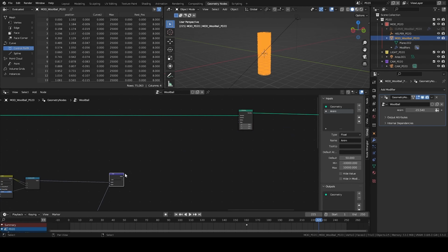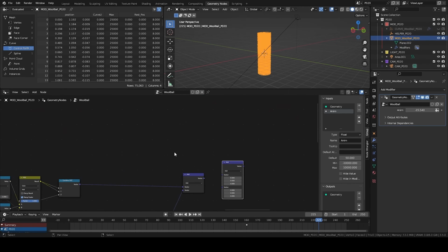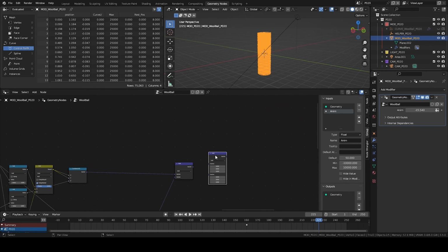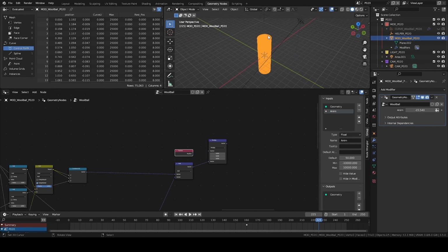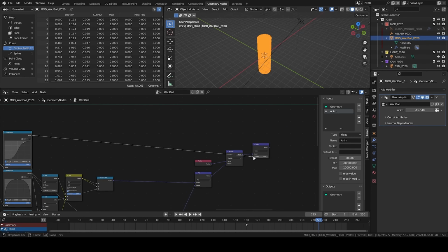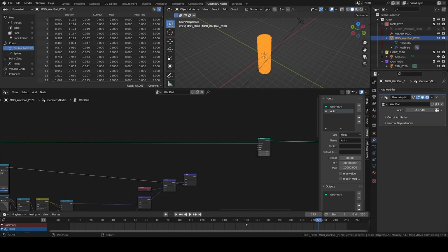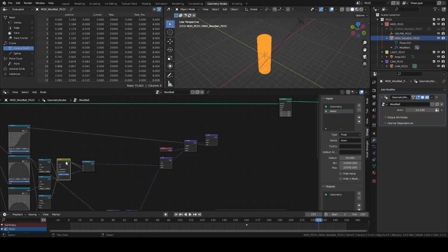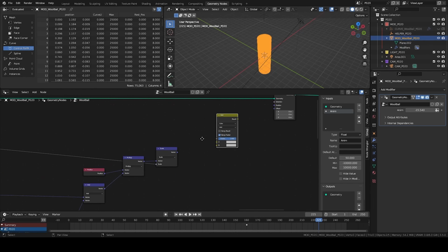And this add node is going to come into a multiply node, and we connect the first curve that we created to all of this afterwards. Multiply, connect it into the second input. I multiply the position that will allow me to shift the curve before it lands on the surface. And there, now I'm going to create a scale node, and in the scale amount, I put my animation curve. All of this can be mixed between the transform position and the source position of the curve.